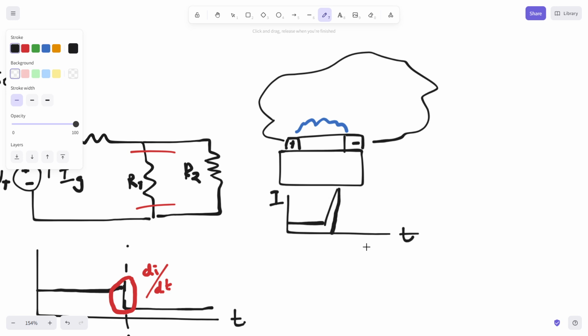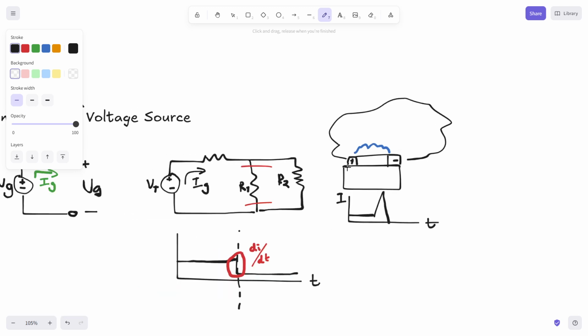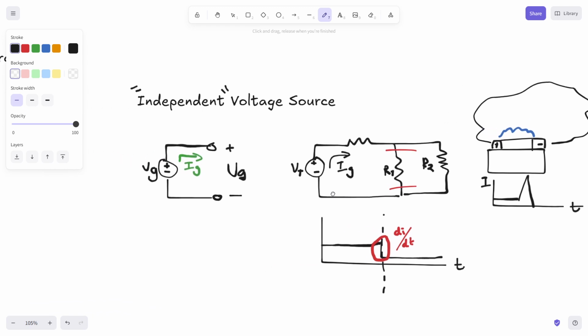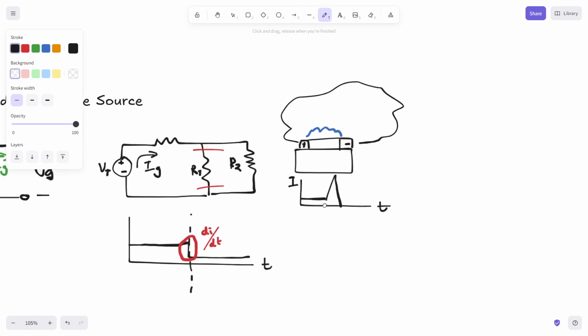Now, in all likelihood, very quickly, if you leave the Allen wrench or the socket wrench there, that battery is going to drain pretty quickly because it can't handle that much current. Or you might destroy something, like destroying your socket wrench. I've burned a few in my time as a mechanic. So this is an important concept to understand, just for safety, just for worrying about what you're dealing with, because this current IG can get pretty large.